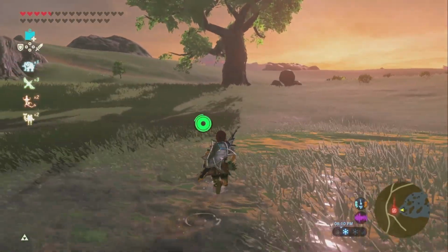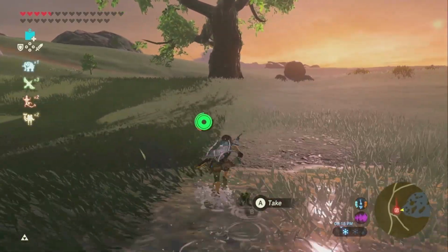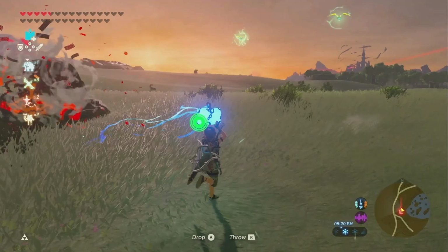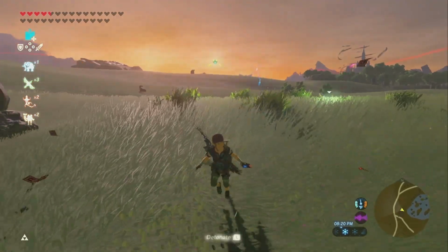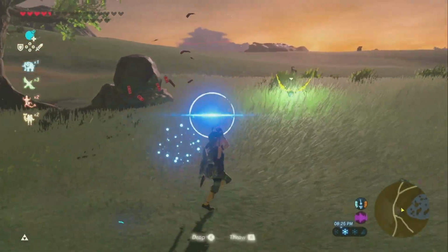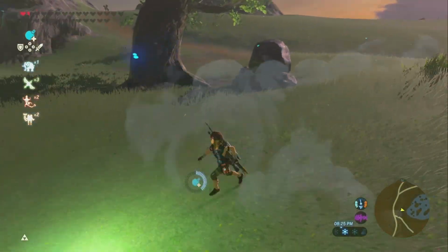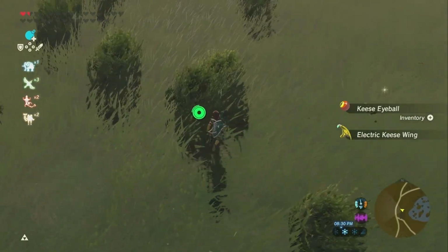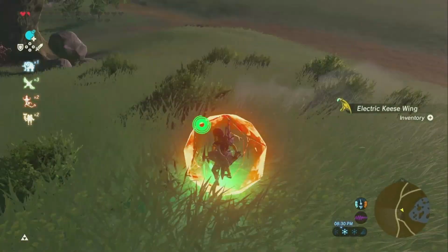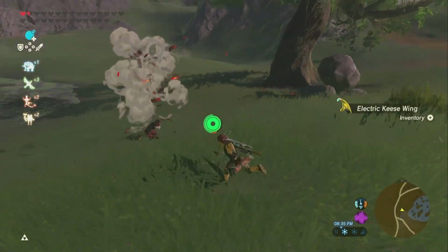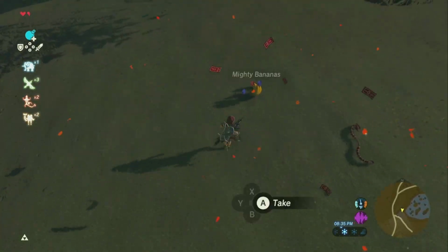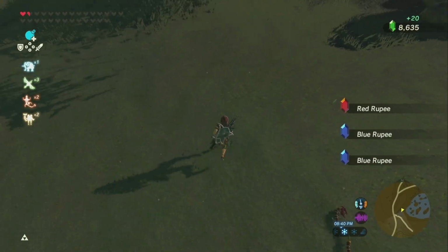The supply of fresh water constantly moving through the water heater exposes the tank to a much more hostile environment than a hot water boiler. A boiler recirculates the same water, which becomes almost chemically inert over time. The fresh water flowing through a water heater is chemically active and contains lots of oxygen for corrosion. Water heater life is usually less than the life of a boiler.